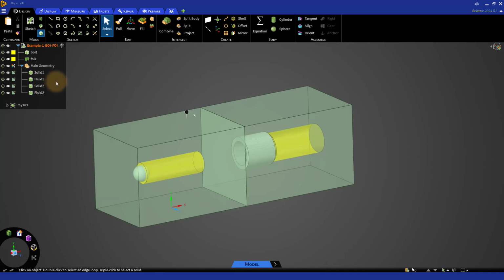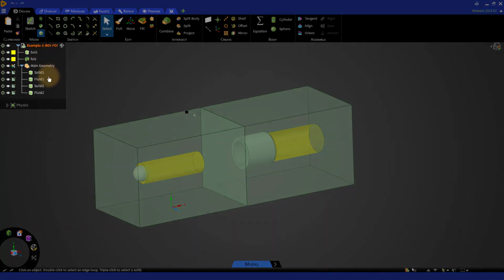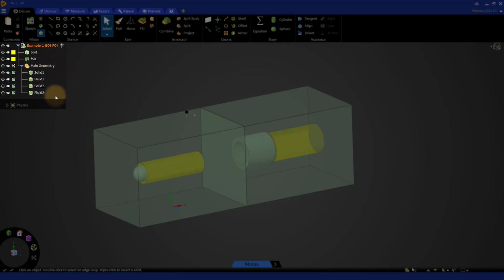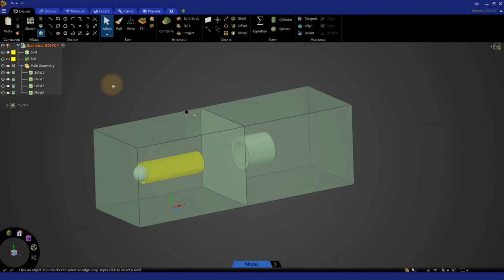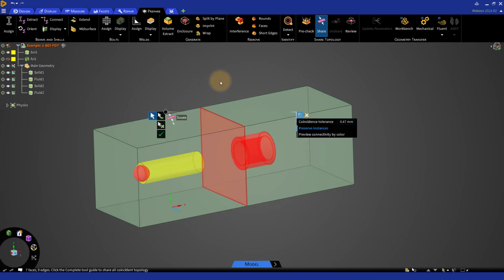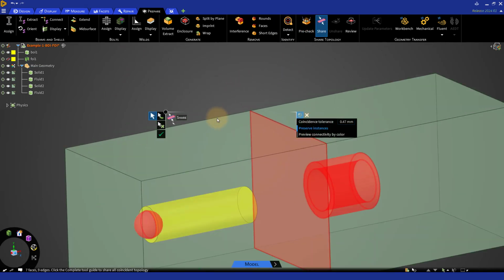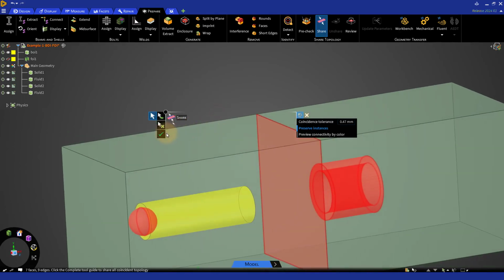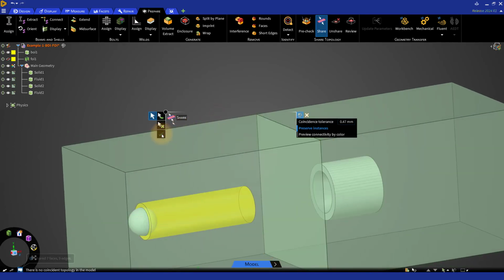For example, when using Ansys Discovery, care needs to be taken such that the BOIs are in a separate component than the actual geometrical entities that need to be computationally modeled, as shown here. This avoids any shared topology features between the BOIs and the geometry to be modeled, thereby allowing the users to define BOI-based mesh refinement zones.